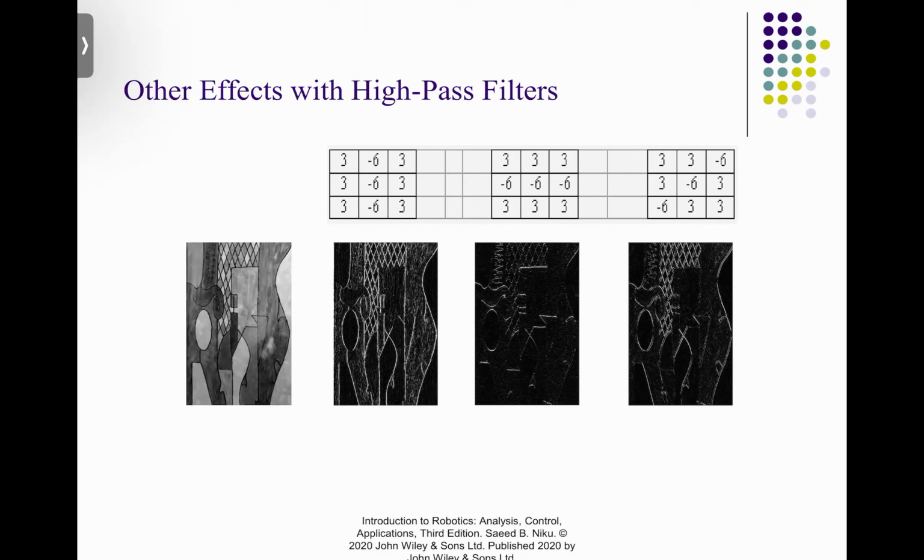Please understand, an image is static, which means once you take a picture, once you take a photo, what you have is a matrix. It's not a signal that is time varying. What do I mean by low pass filtering of an image? Low pass filtering means if you have a pixel and another pixel that are relatively close to each other, they are about the same region.